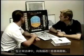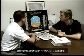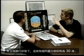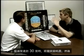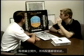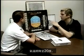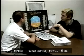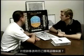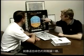In normal law, describe to me some pitch limitations. For example, pitch up and pitch down. Okay, as opposed to pitch left or pitch right? Exactly. Maximum pitch we can get on this aircraft in normal law is 30 degrees. As we get to 30 degrees, energy is going to deplete, and then it'll be limited to 25 degrees. That's true for all configurations except for flaps full. In flaps full, we're limited to 25, and as energy depletes, it'll decrease to 20 degrees. Nose down, regardless of the configuration, the maximum is 15 degrees. And what indications will you see that you have that protection? You'll see green tick marks at 30 and green tick marks at 15, just like these green tick marks.